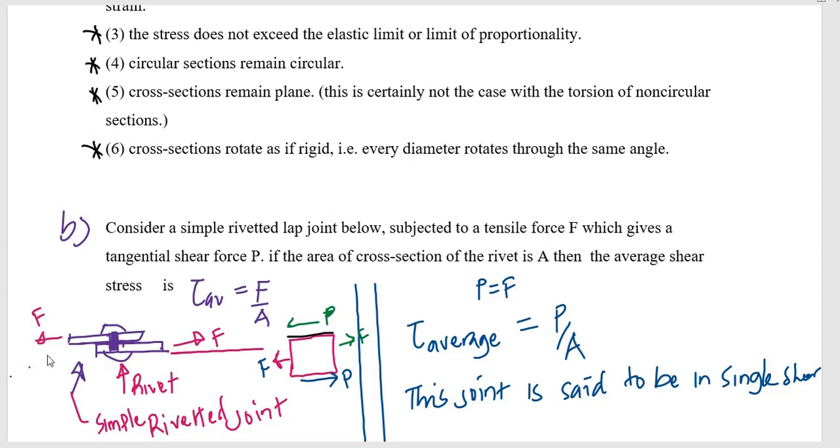So when you look at this kind of simple riveted joint, if I apply a force F and another force here, I'm trying to shear out this joint, and therefore it is realized that during or after failure, this pin is going to break into 2 pieces.